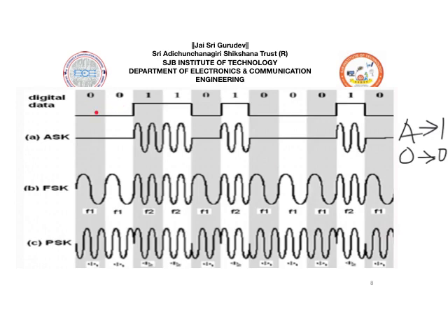Accordingly, if I check this digital data, for 0, the amplitude will be 0 volts, again 0, the amplitude will be 0 volts. For 1, we are getting a sinusoidal wave of the carrier signal. Similarly, 1, again a sinusoidal wave of the carrier signal which has amplitude A, 0, so 0 volts. Again 1, there is a sinusoidal signal with amplitude plus A and minus A, again 0, so 0 volts, again 0, 0 volts, then 1. For 1, again we have a sinusoidal carrier wave with amplitude plus A and minus A, 0, 0 volts. Like this, we are supposed to write the ASK wave considering a sinusoidal carrier and a digital information signal.